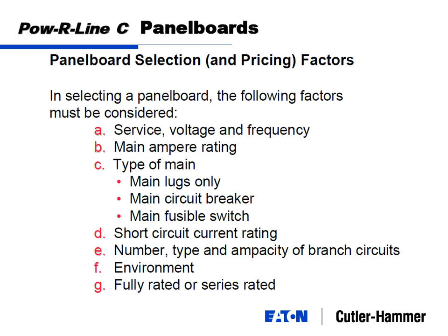So you'll have a neutral wire coming in, so you'll have a neutral bus bar in a 4-wire system, and we'll provide a copper bar, a bolted connection between the neutral and the ground. If you guys talked about grounding, then everything downstream, you're tying your neutral and ground together.